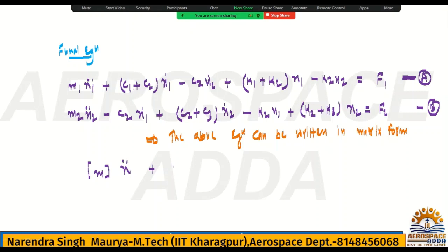So I can write the damping coefficient matrix with x dot. All of c1 plus c2, c2, c2, c2 plus c3 will come inside this, because this is the damping matrix. And then we have the spring stiffness k1, k2, k2, k3, and k2, and its coefficient is with x. So we write the spring stiffness matrix, and the displacement x will come.